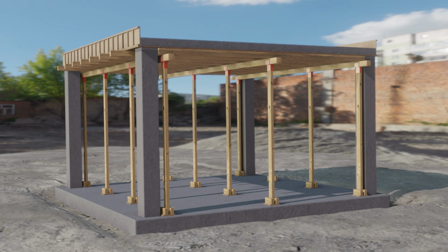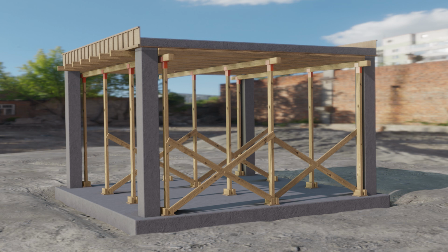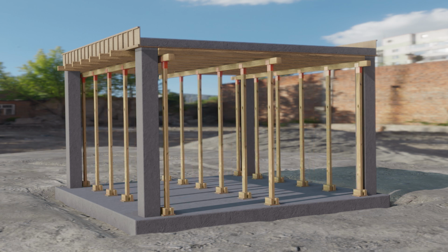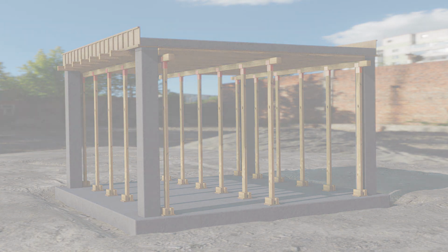There are several alternatives that could have been used to prevent the shores from buckling. The first alternative is to reinforce or brace the shores, which reduces the slenderness ratio of each shore. Another method is to select thicker shores, which also reduces the slenderness ratio in each shore. Lastly, the spacing of the shores can be adjusted. However, the best alternative is to properly design the shoring system from the beginning, to prevent a costly and dangerous incident from ever occurring.